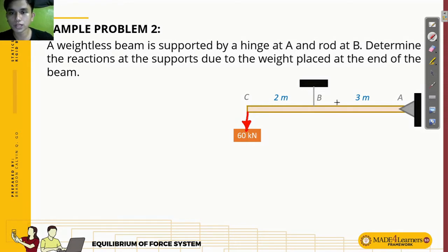And then, of course, there are resisting reactions. So, there should be three reactions. Okay, three unknowns in the equations. Class, read this. Okay? So, this one is a link, or in tension. Of course, since the load is here, it will pull down, so this is tension. So my assumption is always upward. And then the rest, this one is a hinge, right? So, the hinge, class, has two reactions: a y and an x.